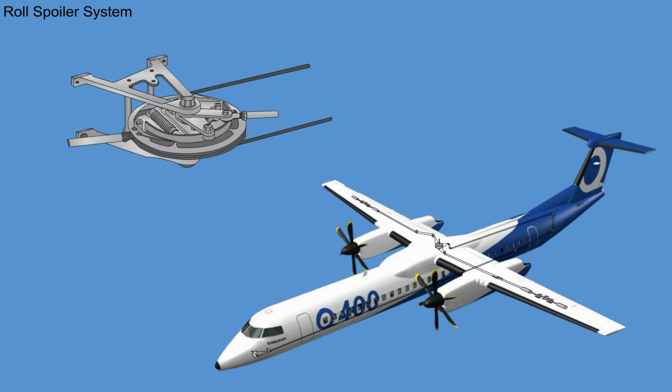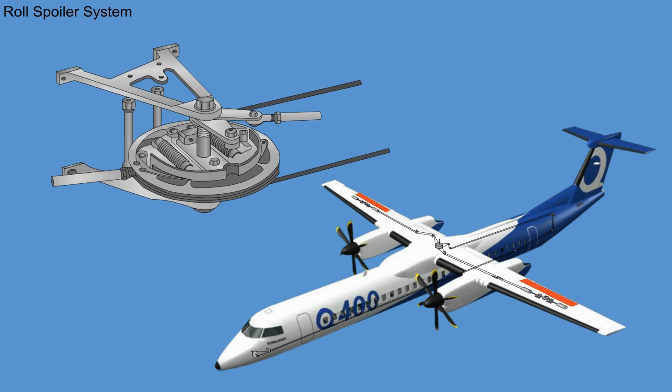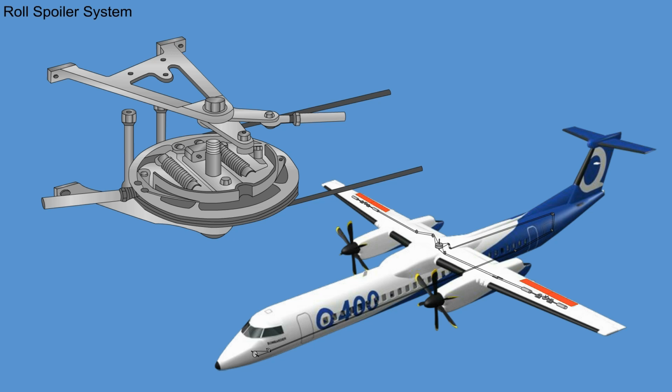The clutch units, one in each wing, are installed centrally below the 2 spoiler panels. The units contain clutch mechanisms to allow for a jam in the controls for either spoiler panel, while keeping control over the remaining spoiler system. In case one spoiler system jams, the clutch plate will be depressed against the springs to disengage and isolate the affected spoiler so the remaining system can work normally.